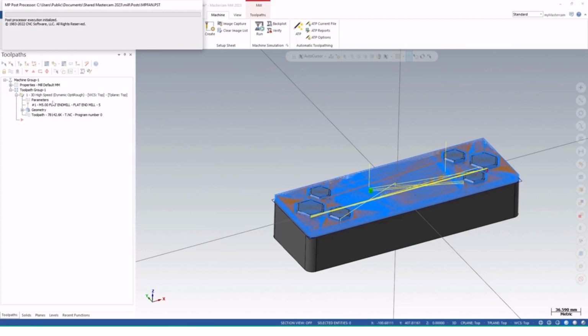Okay, so if you go and change your parameters, just give a 5 mm depth of cut and a step over of 2.5 millimeter, it will create fewer G codes.